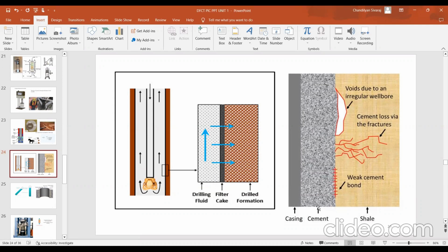That means that is the annulus here, the outside annulus. So if there are fractures or micro channels through which the cement could escape, we call that a circulation loss or thief zones. So for that, we want a good cake to be present here, because that will permeate only a little cementing fluid to be lost. Then we save more money. The reduction in loss is profit for us always. So this is what we call cementing fluid escape, fluid loss into the porous formation. That is what we are talking about in this slide.